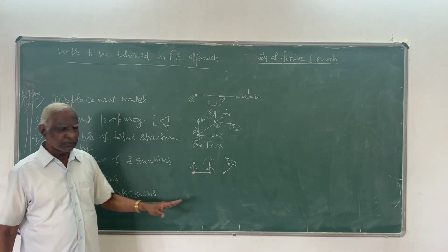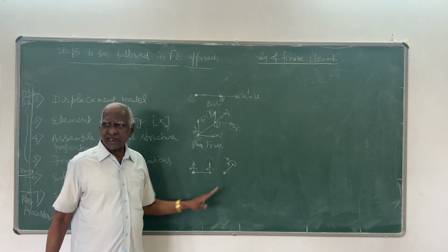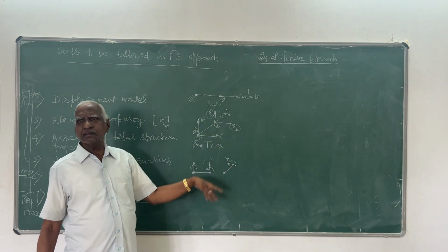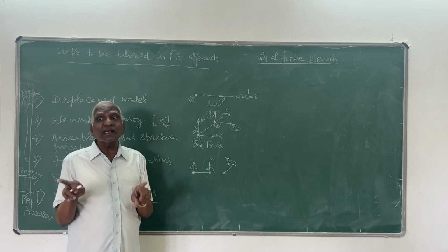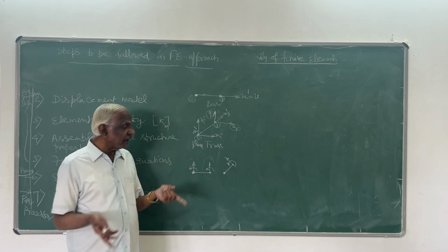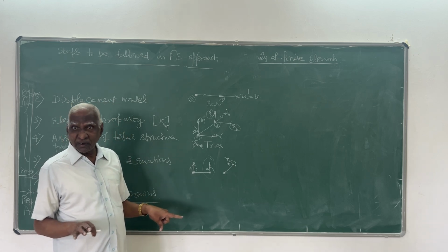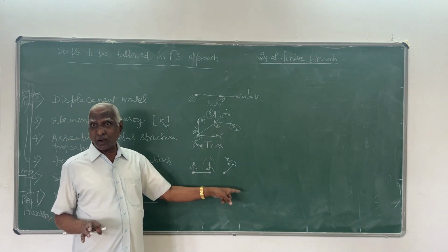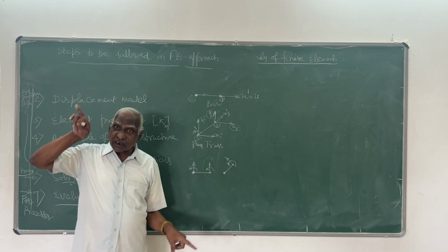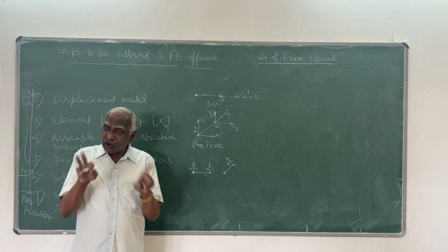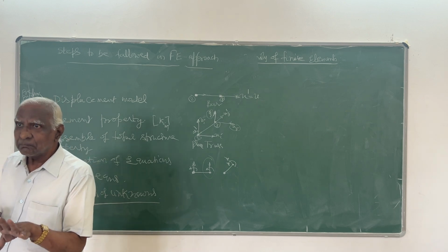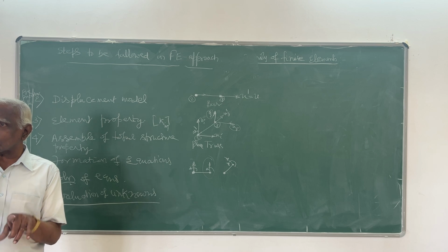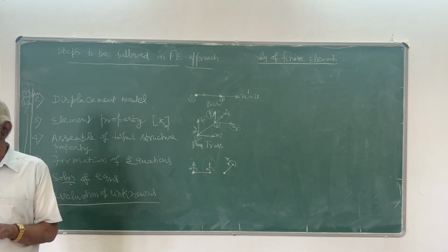Here you have only 2 displacements, one translation, one rotation. Axial is not there. Here also, inclined beam, axial is not there, only shear, even if the beam is inclined. But if you come to global, only the vertical component of this will be there. So in the global direction for beams, you have 3, but in local, we are interested in the internal forces developed only in local coordinates, that you have seen in the classical approach.